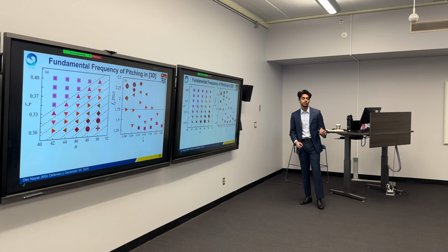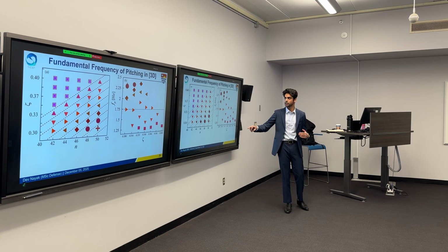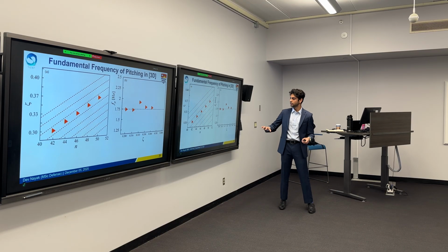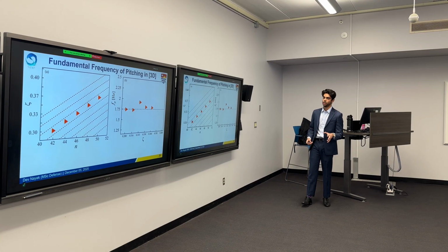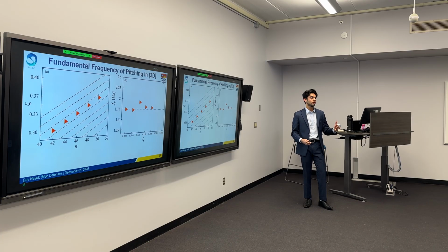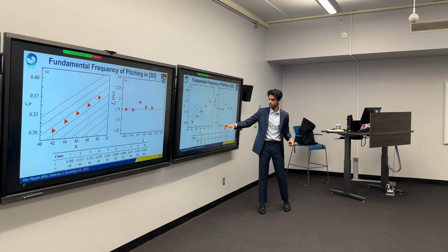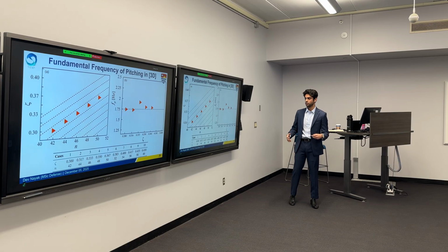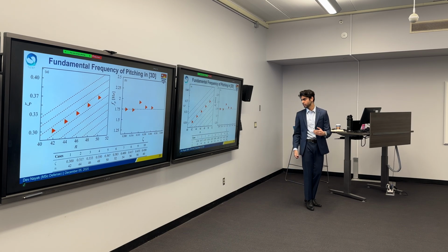Now, for that, we ran a variety of simulations with variation in the controlling parameter n and the damping ratio zeta, from which we moved forward with the investigation where the fundamental frequency comes very close to the heaving frequency, which is 1.75 hertz. And that comes from this Strouhal frequency of 0.3. Because this configuration in the diagonal showed prominent results, we further increased the range of the simulations to zeta 0.450 and n equals 60.